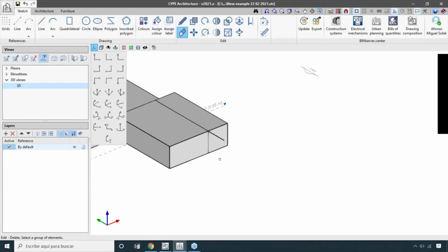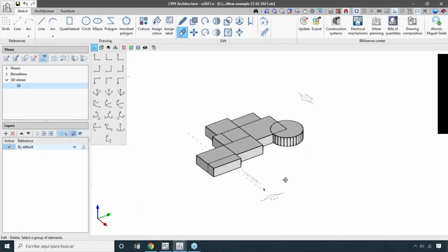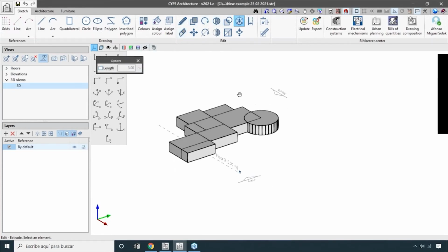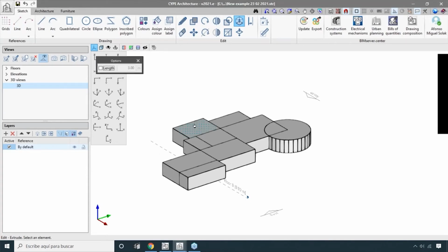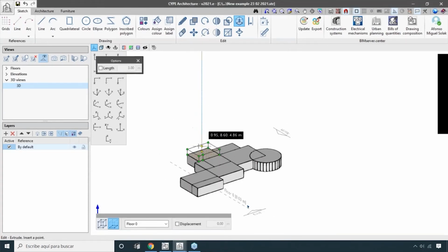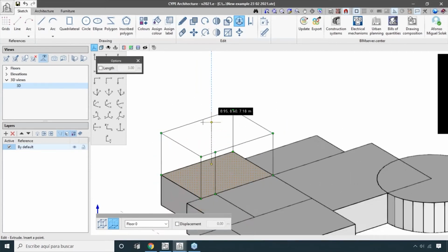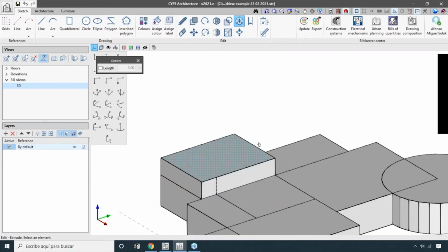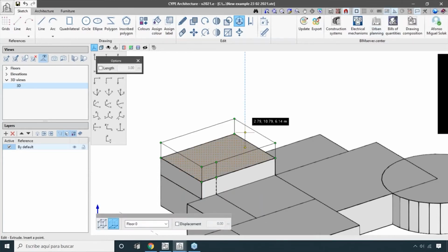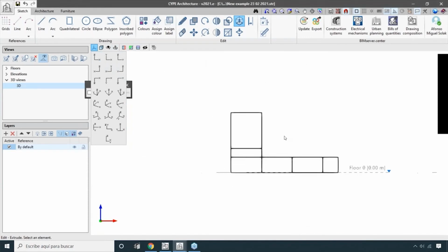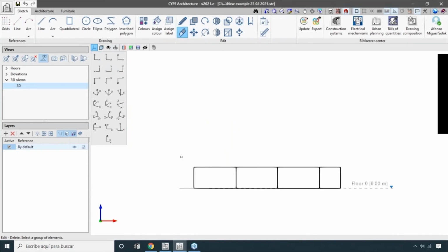Let's delete part of this. Okay, there's another way to extrude something. For example, not activating this button here, with a free length. When we click on that, you just have to work with your mouse and define the size of this extrusion. Okay, let's suppose it's gonna be here, or you can also activate this button here, and now you have a specific length. Let's suppose it's gonna be 7 meters. Okay, so both ways work to create a new extrusion here. Okay, let's delete this part.